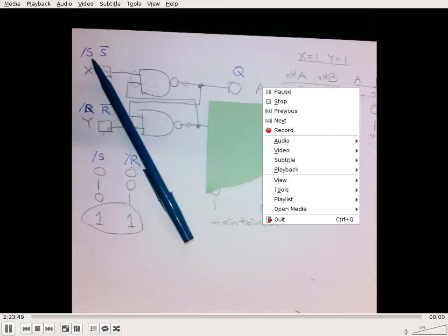The input voltage onto your transformer is going down, but not quite to 0. Okay, so normally we have 110, 115 volts. Maybe it's getting down to 65, 57-ish, that sort of thing. That is really bad for circuitry because at that point your circuitry can no longer truly distinguish between what is a 1 and a 0. So the function of your computer will now go haywire.